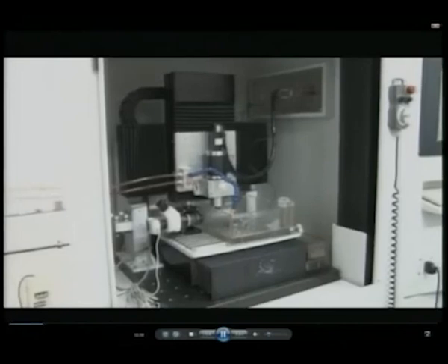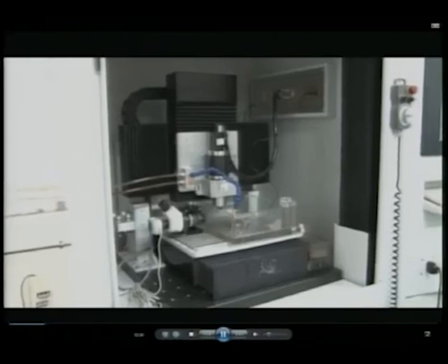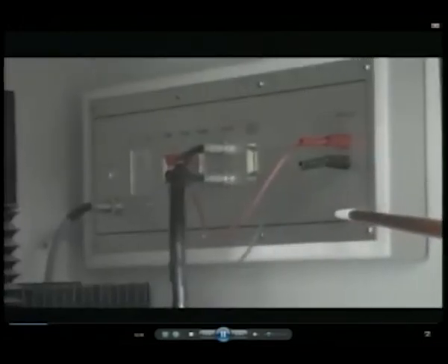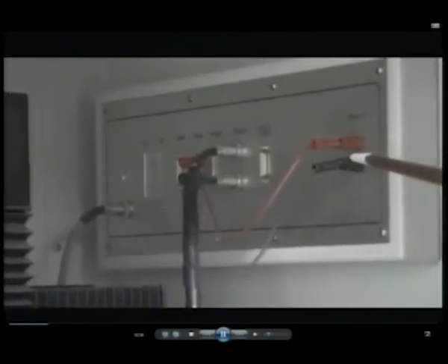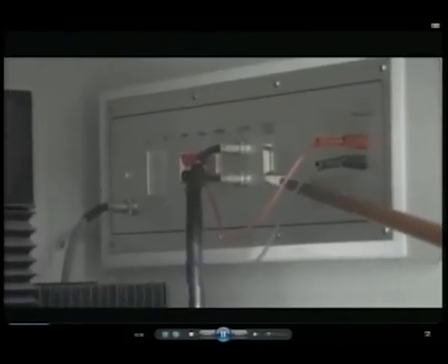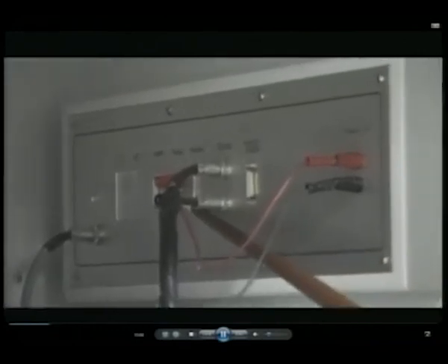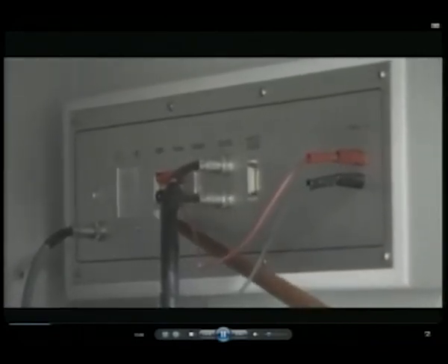For EDM process, 2 elements are very much essential. One is the power supply, another one is the dielectric. For power supply, the machine has 230 volts input supply with 50 Hz frequency. For the feasibility and easy accessing of the electrodes to the power supply, a power board is kept closer to the table. This power board contains a port for EDM, port for wire EDM, port for spindle, port for touch probe and port for OMM.